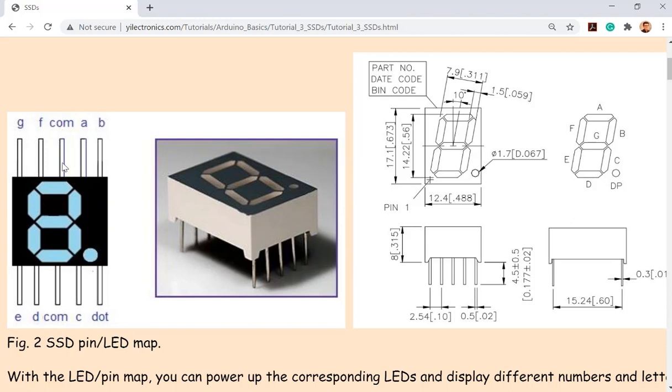So these pins are internally shorted actually. So you don't have to connect both to the ground. You just need to short one to the ground. Before you short it to the ground, do not forget to connect a 1K resistor in the middle, so you can protect the LEDs. So like from here, a 1K resistor, ground. Done. You don't need any other resistors. Is that clear?